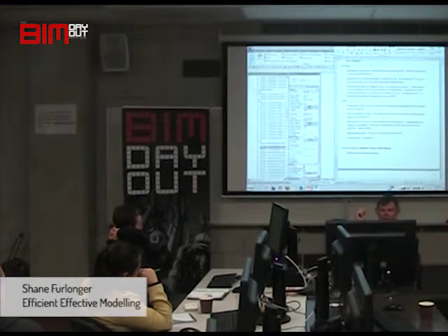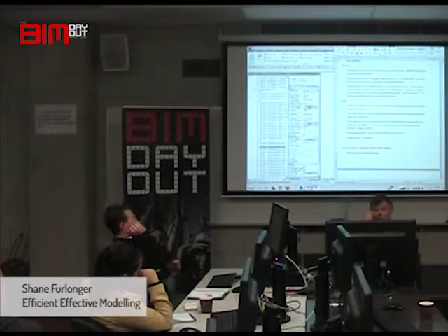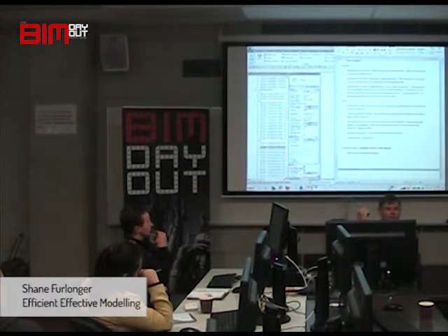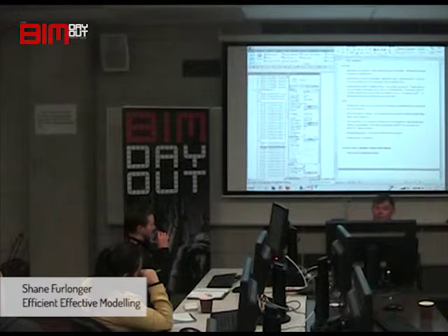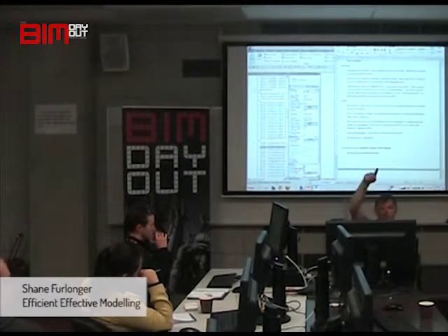If you've changed that half a dozen times and you go and dimension between the levels, you'll find that it's 1 millimetre out from what it says. You've got one that says 10 metres, one that says 12 metres, and your line in between says, instead of 2 metres, it says 1 metre 999. Why?